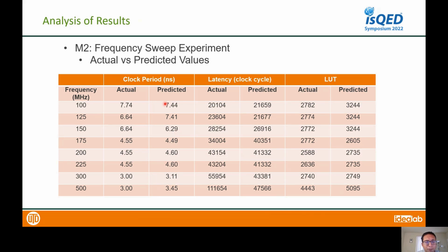As you can see, the values reported by our tool after the machine learning model closely correlate with the values reported after post-route, or after routing. We also ran experiments beyond 500 megahertz, but it has been found that the value reported at 500 megahertz by the Vivado HLS tool remains more or less constant, and the tool crashes after 800 megahertz. Basically, it cannot synthesize beyond 800 megahertz.